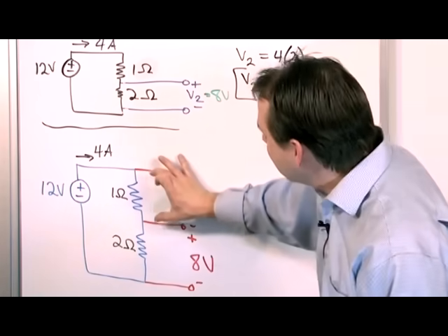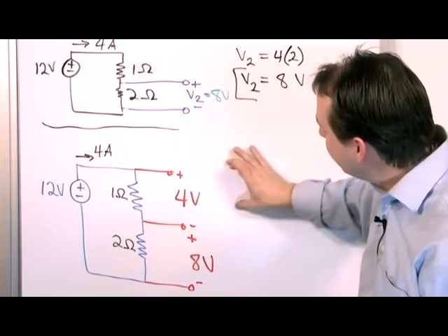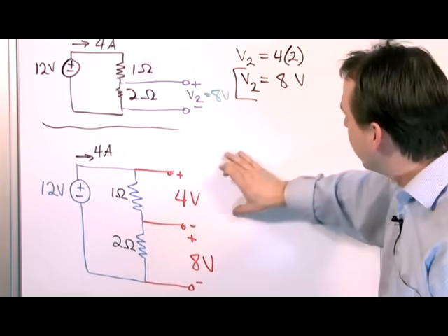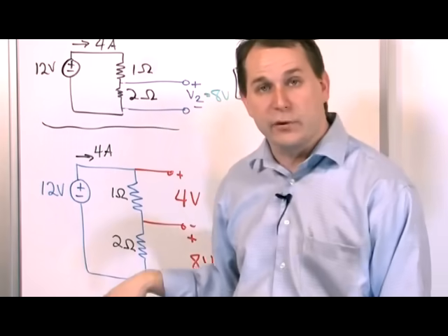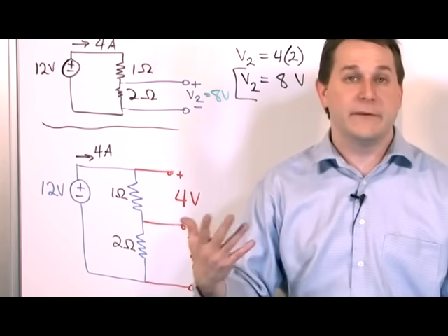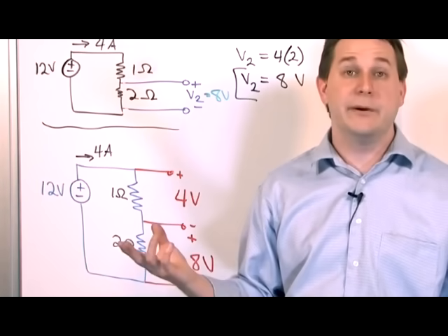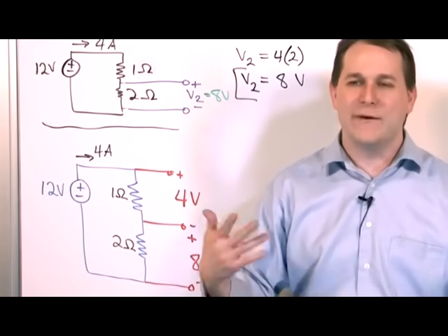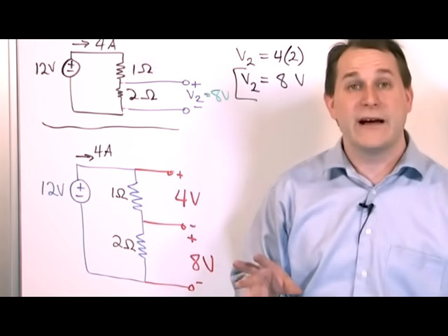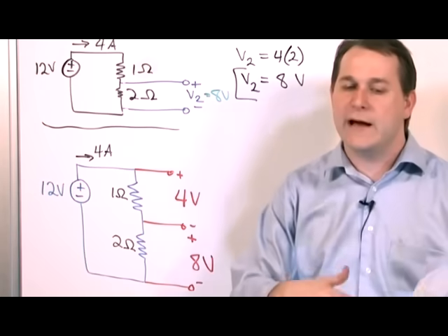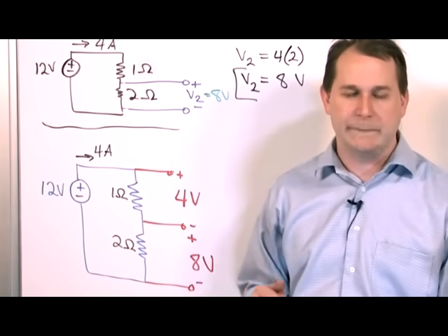So I could take my delicate circuit over here and build it and wire it up right here to the 2 terminals here. The 4 volts would then be supplying my little delicate circuit. The rest of the energy would be going through over here. So a voltage divider is something very practical if you're building something and you need to control voltage, right? At least from a big picture point of view. It's not something you do every day in really delicate equipment where you're trying to get really precise things, but it certainly works in a pinch if you have a few components laying around and you need to convert a voltage. It's a very easy way to do it.